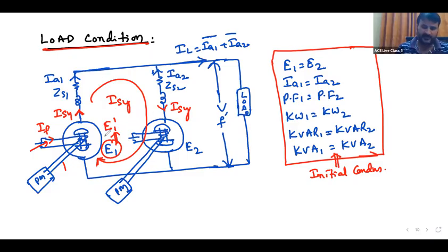And this reactive power, what will it do? It will demagnetize the first machine and magnetize the second, same story. That is the same. When excitation of the first machine increases, the set terminal voltage increases. Whatever conclusions we made under no load condition, here also are totally valid. But what happens to the powers is what we are going to mainly focus on.